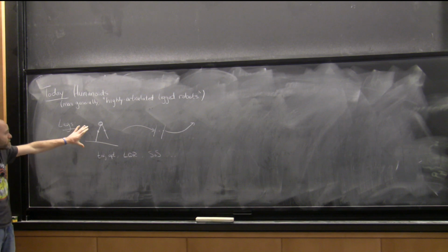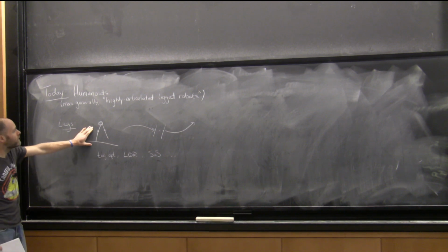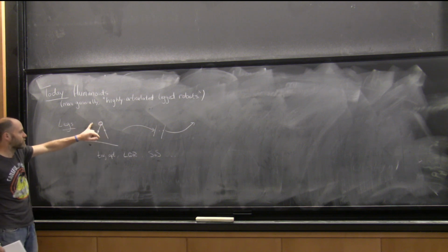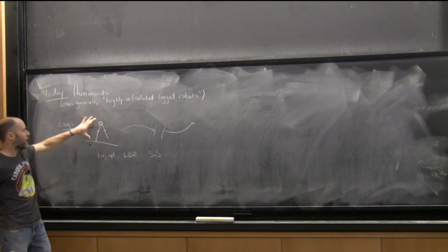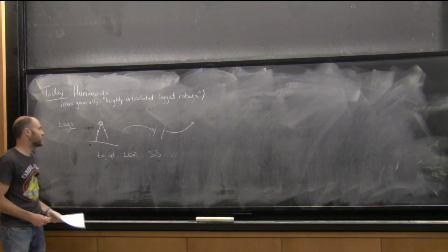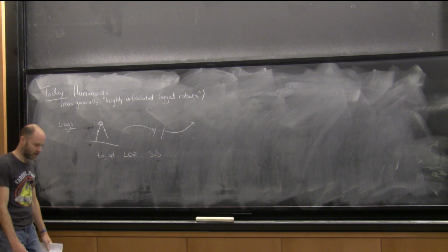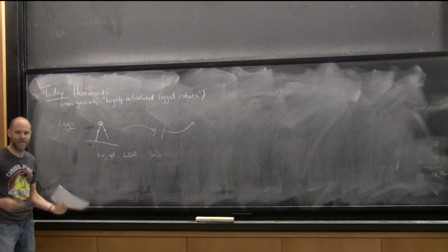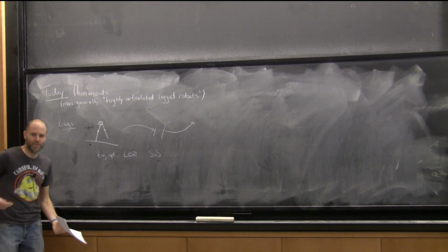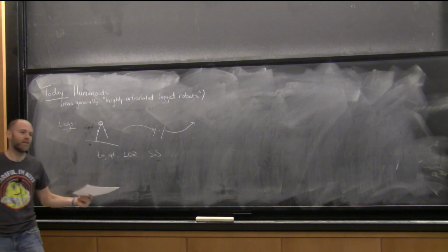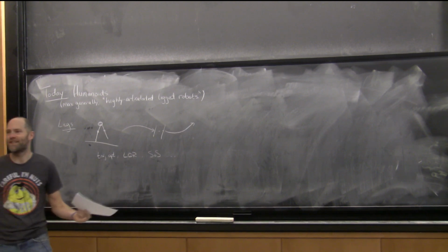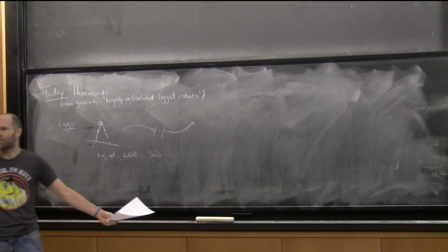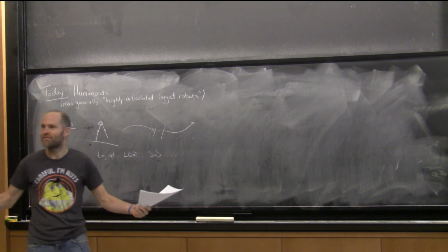Okay, so this path is one where there's a lot of work to do nonlinear optimization, even for a 2-link robot. You have to be careful about the guards. If I go to a kneed robot, it gets a little more complicated. If I want to add 2 knees and an ankle, it's getting more complicated still. My nonlinear programs are running more slowly, and I'm less sure they'll find a solution. I add a hip and arms, and I feel like the weight of the universe is coming down on me because my optimization is not going to be as strong. But at the same time, I've shown you videos of full-on humanoids running around. So something doesn't compute.